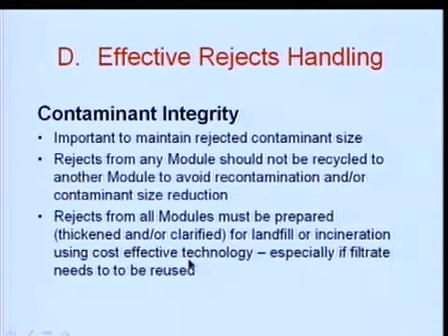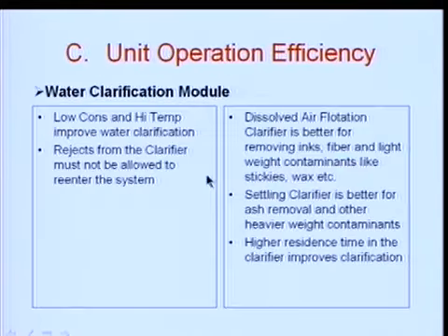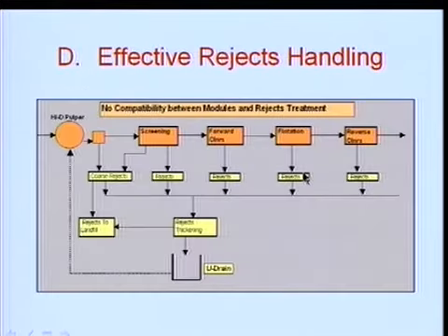We just talked about that. All this water is full of all this contamination, which is fiber, lightweight contamination like stickies, waxes, etc. So once you do that, what have you done? You basically increase the load on the rest of the system in terms of lightweight contamination, stickies, and some sand, some grit, and now all of these are going to get overworked and their efficiency is not going to be as good. So overall system efficiency goes down. Sure, you have saved some money here by not treating this water.